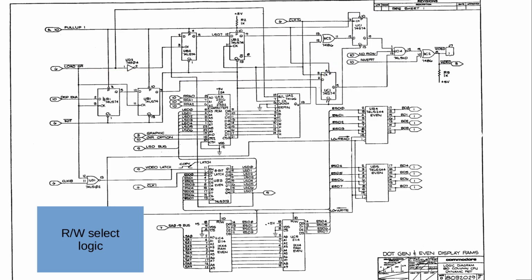rather simple. You have the display enable delay, which is done by load shift register. The shift register load is here 2 cycles, and then you have the inverse bit delay, which comes here from the RAM data bus 7, or from the latch. From the latch it goes up here and is delayed. This is all in the block diagram, and then goes here to this XOR gate where the shift register output comes, and then it's synced with the main pixel clock again.